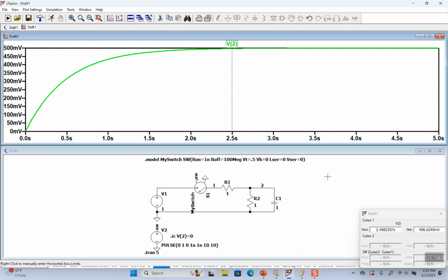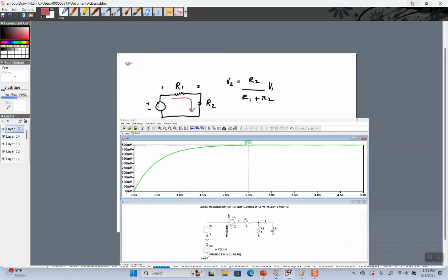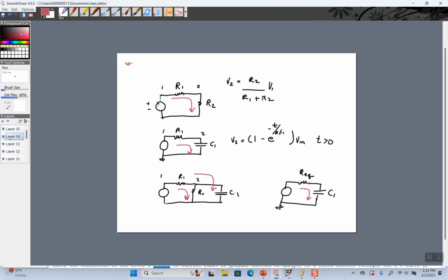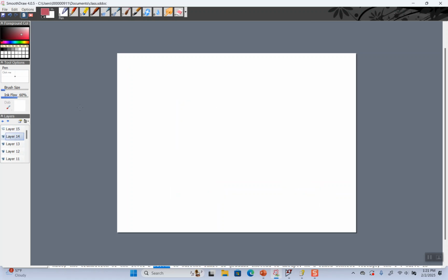We're getting within 5 tau a little sooner. And just a quick review, tau can be many things, but it can be an equivalent resistance times an equivalent capacitance. For some kind of step response, you would have 5 tau. Why tau?